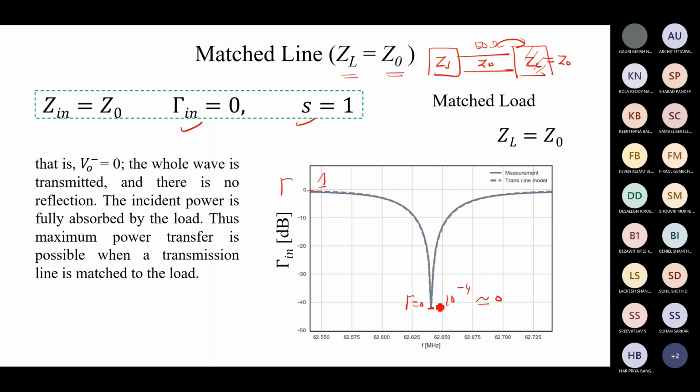If the reflection coefficient is 0, what is the meaning of that? The signal is going from here to here, there is no reflection. But what about here? All the signal is getting reflected before reaching the load. So this is giving a selective transmission to a load. For a given load, only a certain range of frequency alone will be allowed. The remaining frequencies are not allowed. So this is a very interesting thing, that I can properly send a signal within this so-called bandwidth.